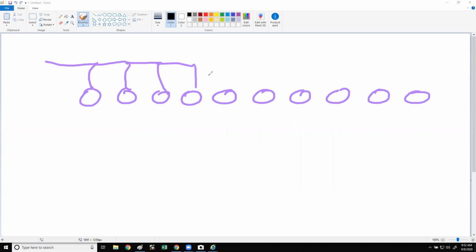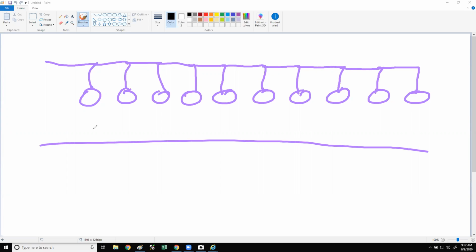so on and so forth. So let's say this circuit, photo eye closes at night and it's supposed to energize a contactor coil that turns all these lights on. Okay, and here's the neutral. I'm not going to connect the dots, but let's say that circuit breaker, I don't remember the symbol for a breaker, so I'm just going to put a fuse. Every time it turns on, you blow the fuse. Uh-oh. What do you do? Something here is grounded.